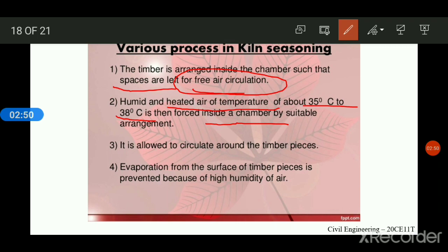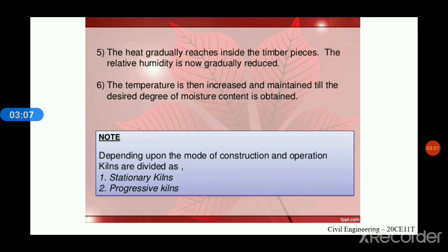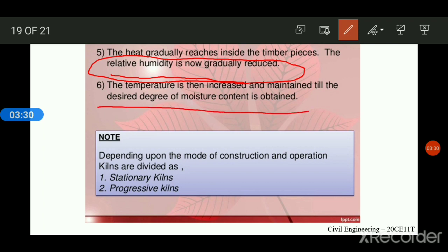It is allowed to circulate around the timber pieces, and evaporation from the surface is prevented because of the high humidity of the air. Then the heat gradually reaches inside the timber pieces, and the relative humidity will gradually reduce. Finally, the temperature is increased and maintained till the desired degree of moisture content is obtained.